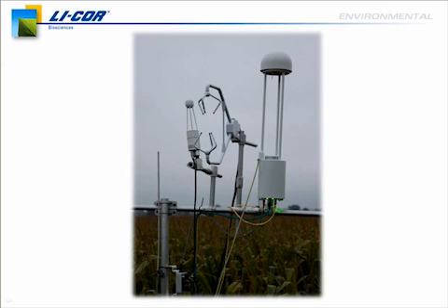This is a flux tower that we had deployed again over a cornfield. So you'll see here the standard instrument bar arm coming off the side of the tower, and we've got the sonic anemometer positioned in the middle, such that, as usual, it's going to disrupt as little of the prevailing winds as possible. Then we've got an LI-7500 to the side of that in a traditional configuration, very near the sonic path, but again, we'd like the air to go through the sonic first before it hits the analyzer.